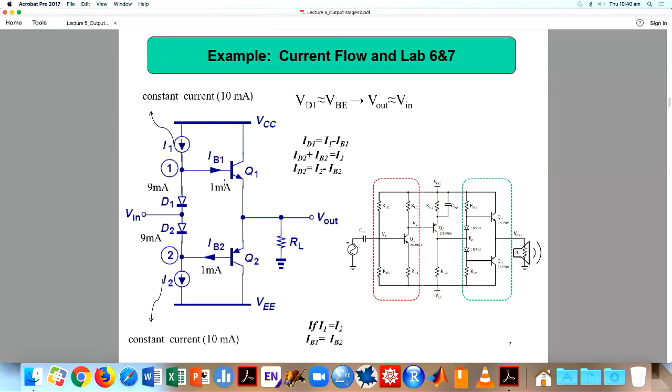So how many of you thought about this amplifier? Because you have used a microphone, then you have got a speaker. That is the reason we got a push-pull stage here, the output stage. Because we want to amplify the current. When you amplify the current, we don't want to have a dead zone. That's the reason we will be using this configuration.